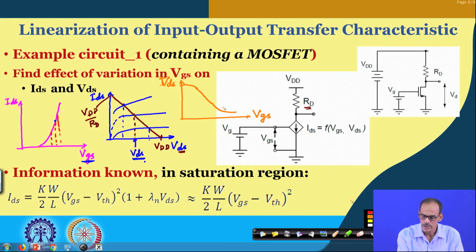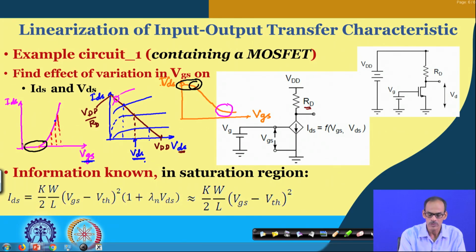So, you may say that this nonlinear part is coming due to the device entering into the triode region. On the other hand, this nonlinear part is coming due to the device entering into the cutoff region. So, the overall transfer characteristic we are getting here, as I said, because of the device characteristic which is fairly nonlinear, we do have a nonlinear input to output transfer characteristic.